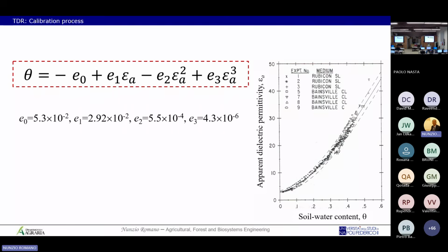It's difficult to always have the same value. It depends on the tool that you use, but you have an average. If you put all these measurements together, you have the mean value, and then you have the minimum and maximum value. So the interval between the minimum and maximum value gives you an idea of the uncertainty.